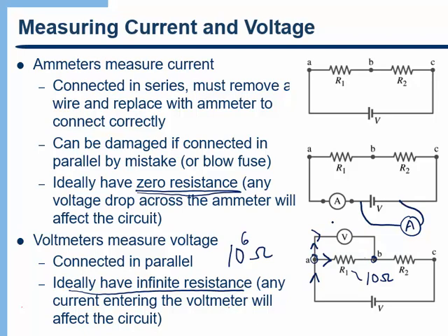So that's an important thing to remember when you're connecting meters: ammeters connect in series, voltmeters connect in parallel.